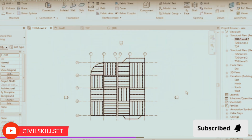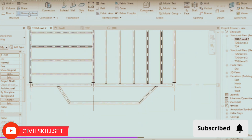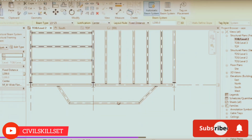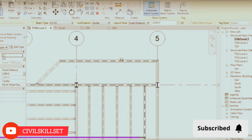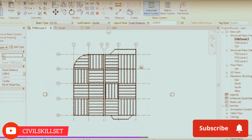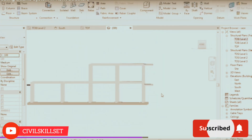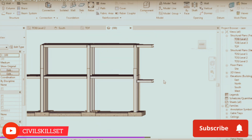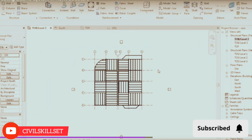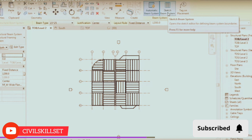The second point is about consoles. In consoles, right, we cannot use the automatic beam system. Let's see the one at the top too. Why do you think we cannot use this automatic one? That's right, because of the height difference there, right? So in these situations, what should we do? That's right, we should go for beam system sketch, or sketch beam system.